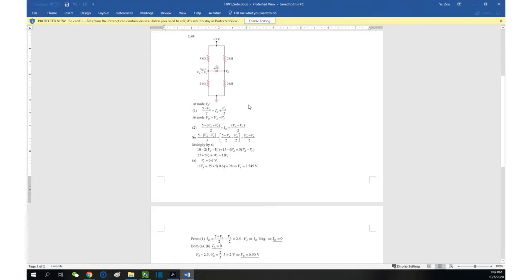But in the exam, remember, we have learned this from the lecture. The proper procedure is you begin with assuming the diode is on, and then you have a reasonable reason to apply that diode model, which is the DC supply.